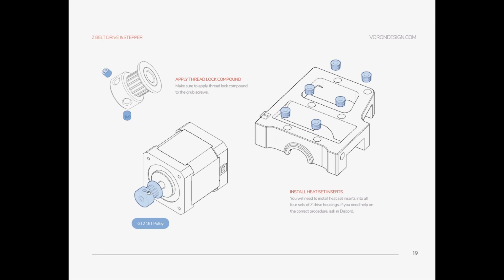This rotor, where the rotational thing happens, should have one flat surface, like a D shape. One of the screws needs to sit on this flat surface. With that, it will hold the rotor longer. There's less chance of it becoming loose, is what I'm trying to say.